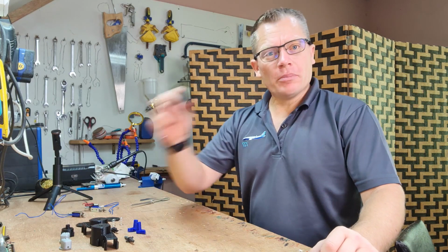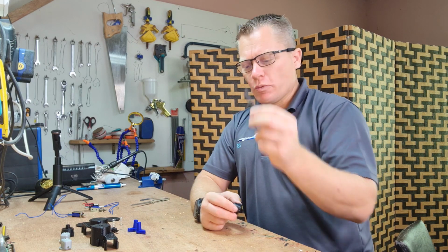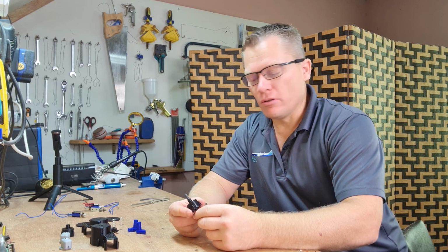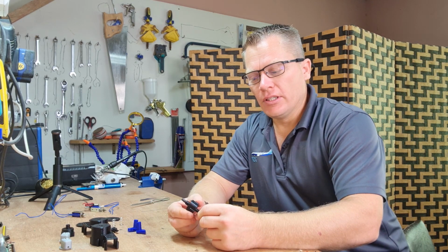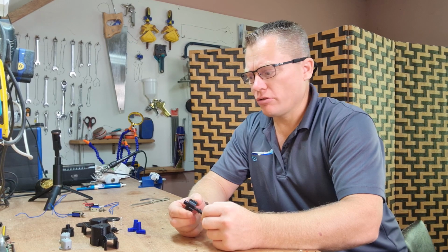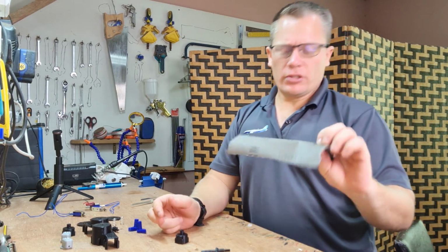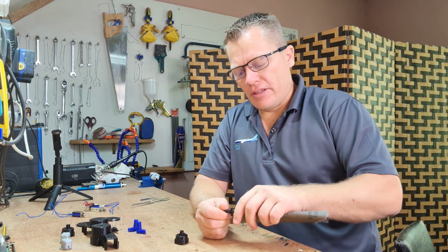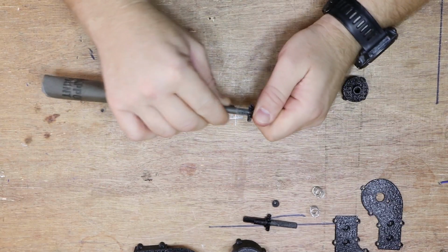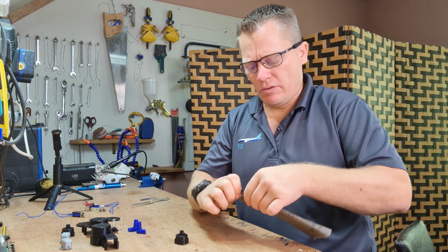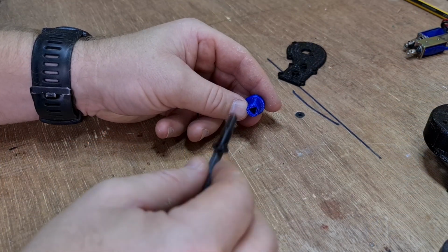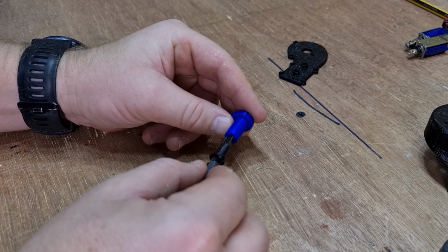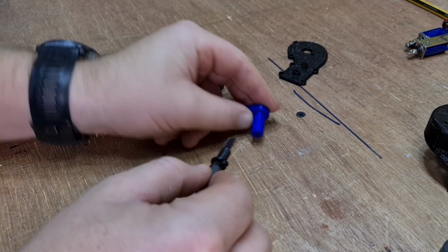Taking our upper body and an actuator rod, we need to make sure that there's smooth operation between the 2 units. I can already feel there's a bit of catching going on straight away. So I've got some 320 grit sandpaper here, and I'm just going to run it down the length of the rod. Make it nice and smooth. I'm just going to try the activation rod into the activation cam and see how it feels. Right, it's going in smoothly, but it is catching on various points.